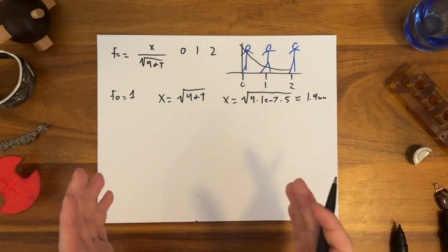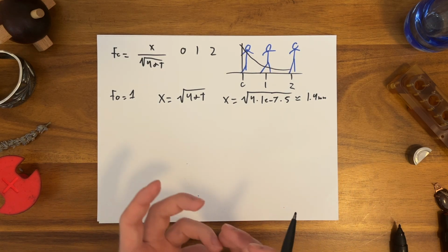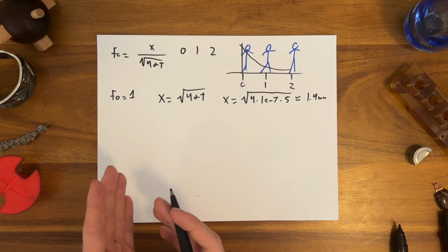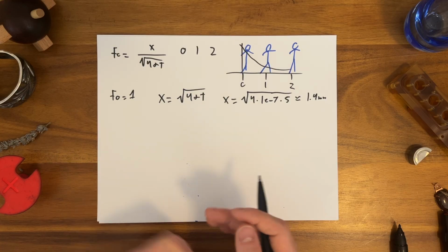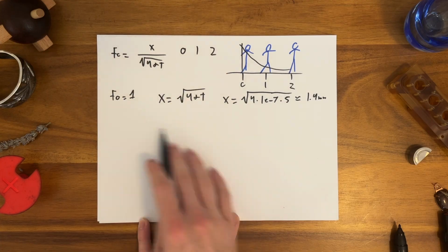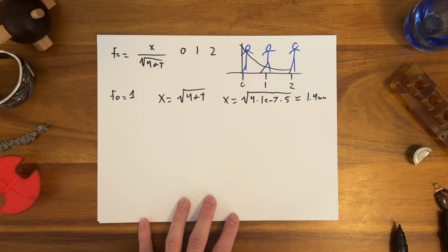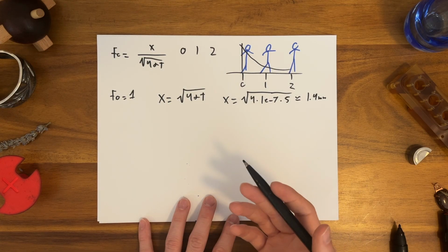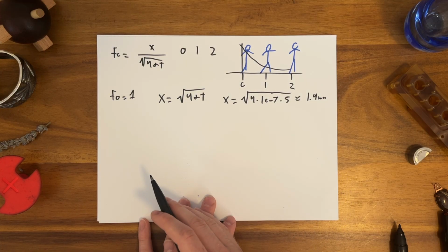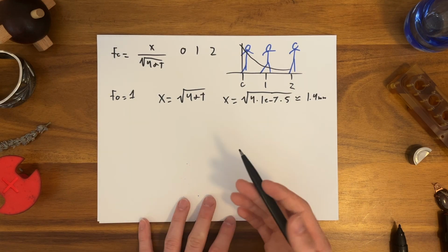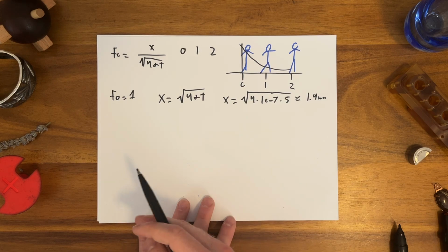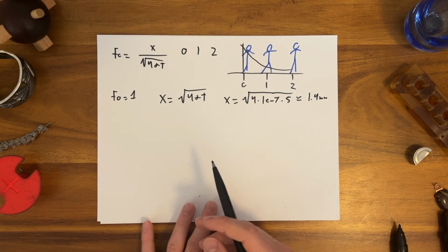So already right off the bat, I know that if I have just a little bit over a millimeter of foam, I'm going to be able to do a substantial amount of insulation and protect my thin aluminum enclosure and have low backside temperatures. If I wanted to push Fourier number to 2, you'd end up with about 4 times as much. Okay, now it's like 6 millimeters thick. This is not a lot of material, and what matters mostly is the thickness and the diffusivity. If I'm looking at a foam and a rubber and they have similar diffusivities, I'm going to go with the one that's lighter and cheaper so I can make it thicker to get the advantage. Again, they're all about 1e minus 7.